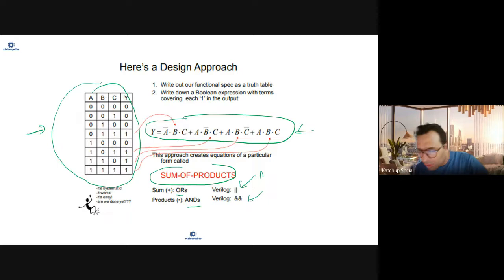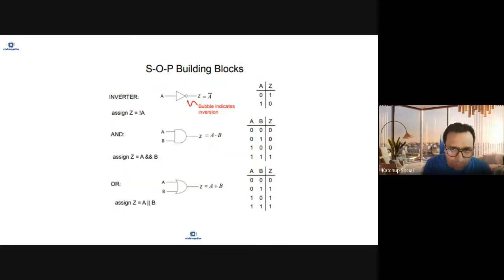So whatever RTL you may have written, the synthesis tool, using multiple algorithms, converts that into what is known as sum of product form. So you write your functional specs in HDL, and the synthesis tool will automatically convert that into truth tables or Boolean expressions, as sum of products.